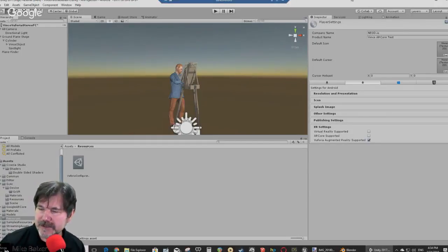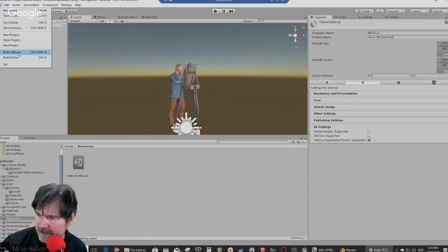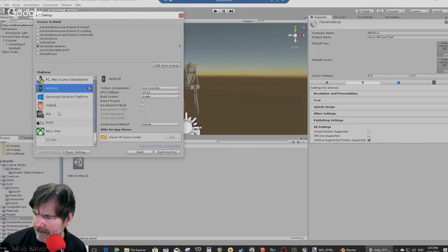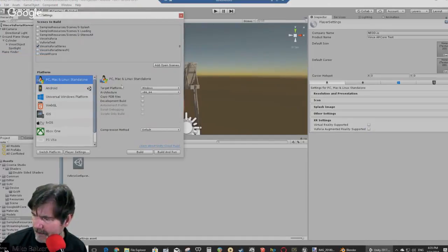Looked at the bridge system. Well, actually start out with a HoloLens, which is the most expensive and pricey. And actually, I should show that. Oh, I'm not there yet. So if you wanted to work with the HoloLens with Unity, it's fairly easy. You just go back in, make sure that you're using the Windows platform right here. And then you go to your player settings.